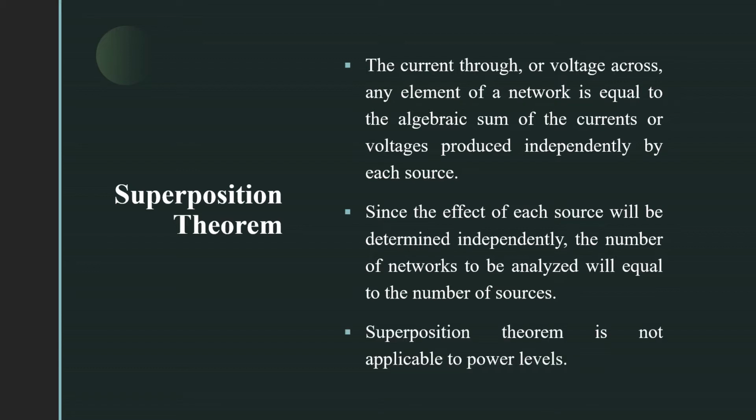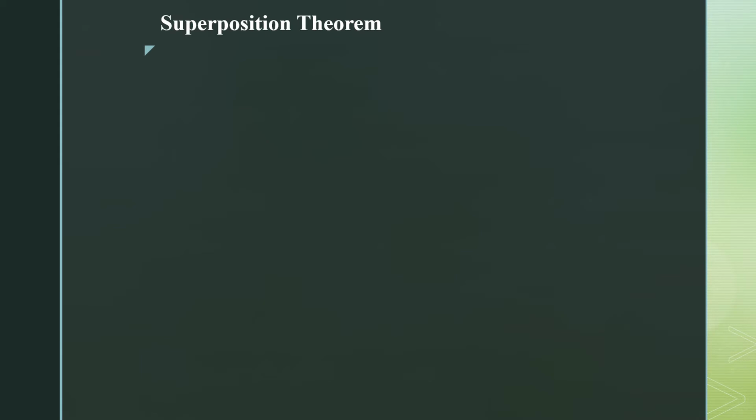Superposition theorem is not applicable to the power level. In our example, we will see that the superposition theorem is not applicable to power levels. If we have multiple sources in our network, we have to take one source at a time and remove the other sources.